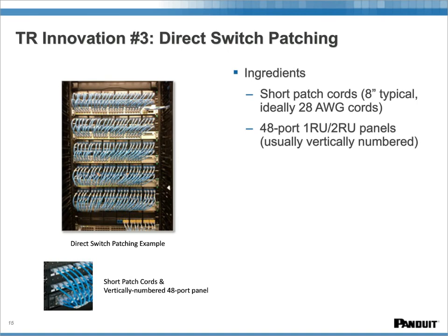And in this case, the switch is at the bottom, and its adjacent patch panel that it patches to is directly above it. Now, it can also be positioned so that it's patched to the panel directly below it, but the only requirement is that the panel to be patched by the 1RU switch is directly above or below the switch. It's your discretion, customer's discretion as to which.